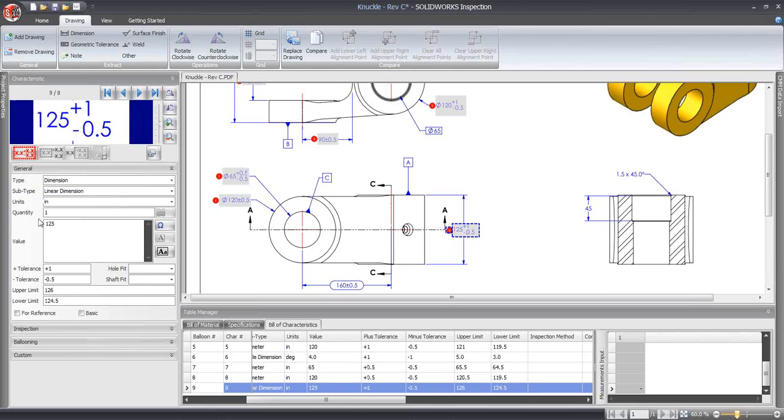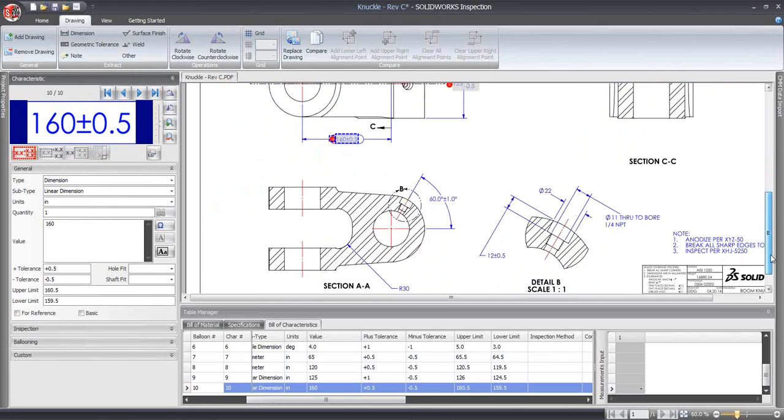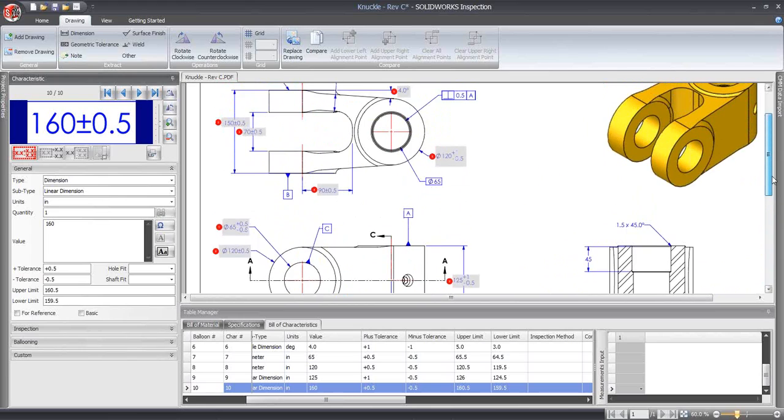By chance, let's say if your tolerances are not getting captured properly, you can just go and recapture them from here as well. So I need to specify that this is my basic dimension. Again, these are my upper and lower limits, so I can select them and specify. It will make the corrections if they go wrong by chance. I'll capture a few more dimensions there. Okay, let's go down. Once they are done, you can just go back.